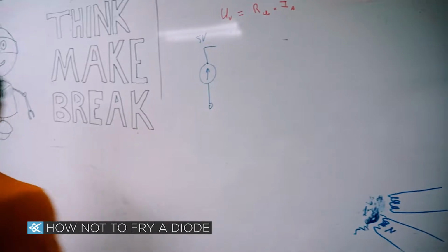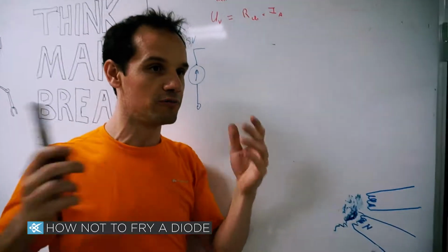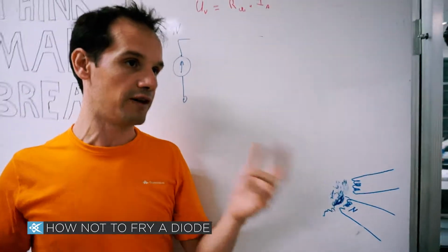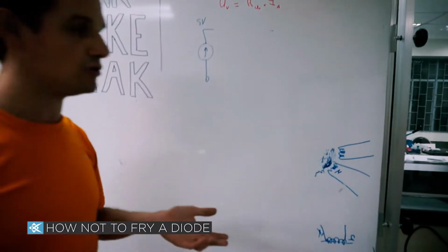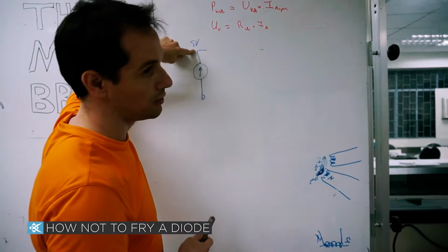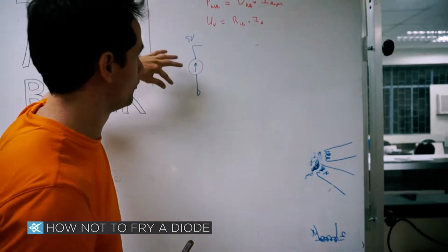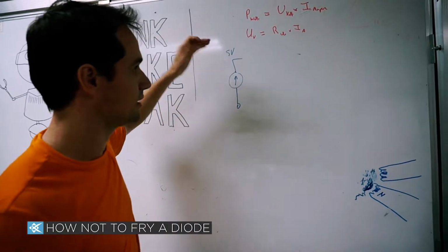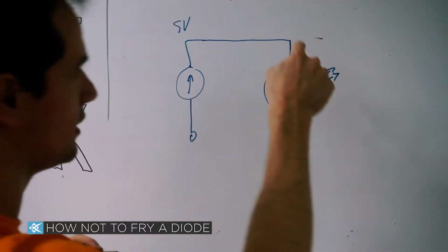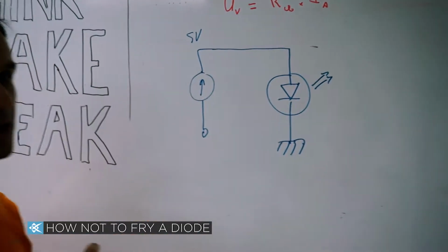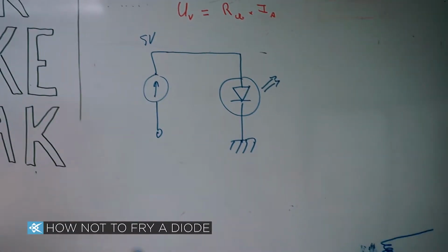So in digital electronics, high or 1 is usually either 3.3 volts or 5 volts, depending on what components you use. But in the basic Arduino, we know it's 5 volts. You have 5 volts coming from a pin. I'm going to assume it's a perfect source of 5 volts and it can send an infinite amount of current, which is actually not true. Put those 5 volts onto that LED and you see it lighting up for a very short amount of time.